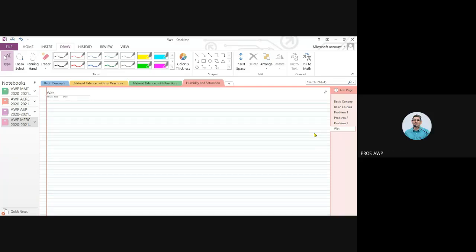But if I do it isothermally, which is more difficult to do, then obviously I will have to look at only the effect of pressure. In the same way, when we are depressurizing, we can do it adiabatically or isothermally. Adiabatically is easier, but yes, the temperature would fall and more water will condense out. But if I'm doing it isothermally, then I just have to worry about the effect of pressure.